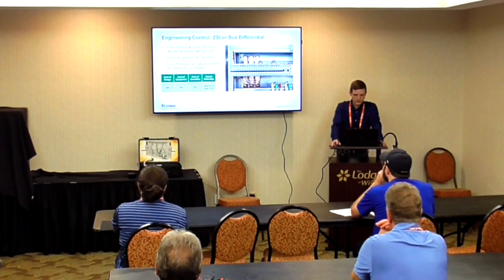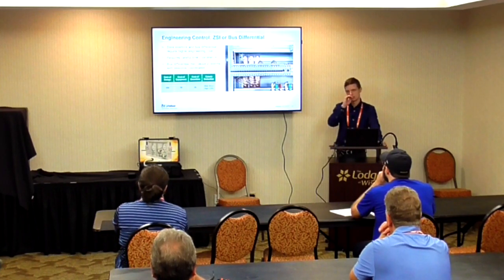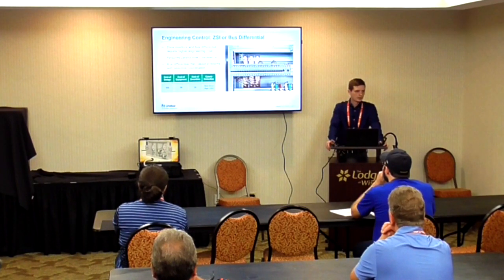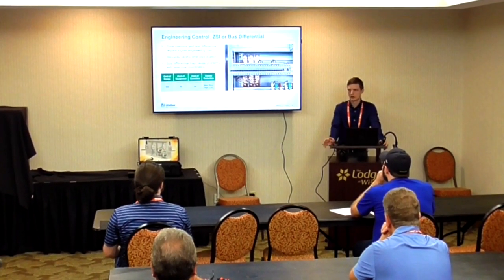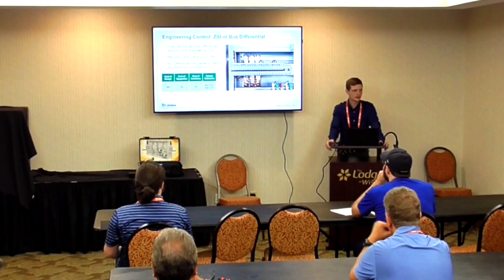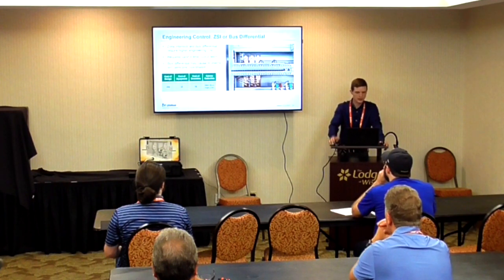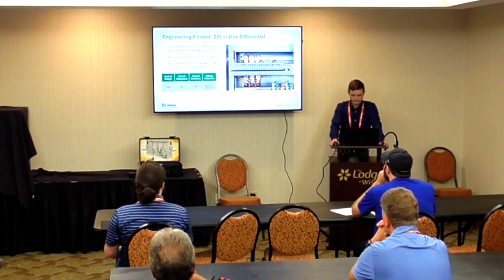Another caveat for the bus differential system is that it can interrupt any selective coordination that you have in place. So a lot of industries are now looking at selective coordination even where it's not an NEC requirement. Reason for this is even without an arc flash, if you just lose a fuse or you lose a breaker, you don't want to lose a lot of your other branches. That's going to cause a lot of unneeded downtime and be a lot harder to identify where your fault happened, things like that. So bus differential can actually bypass any selective coordination that you've done and just interrupt everything at a feeder level. So important to keep that in mind when we look at cost of downtime.